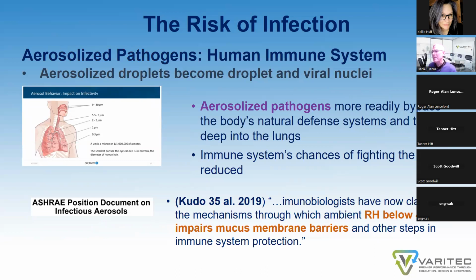So another aspect for humidity is that if virally laden droplets stay in droplet form, they maintain their water content. Then if that droplet is ingested by another occupant within the space, the water content of the droplet will more readily adhere to the wet surfaces of the mouth and nasal membranes and will not travel deep into the lungs. However, if that person ingests desiccated virus, free or broken free of the wetted surfaces of a droplet, that desiccated virus will not as readily be captured by the wet surfaces of the mouth and nose and will be drawn deep into the lungs, where they pose a graver health risk to the person who has breathed in those particles.